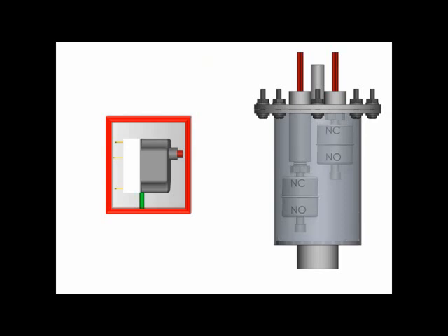To solve this problem, we delime the floats and reset the boiler high limit. Scale in the floats can also cause the floats to stick closed and the water overruns into the oven cavity. If water level issues arise, the first place to investigate is the float canister.